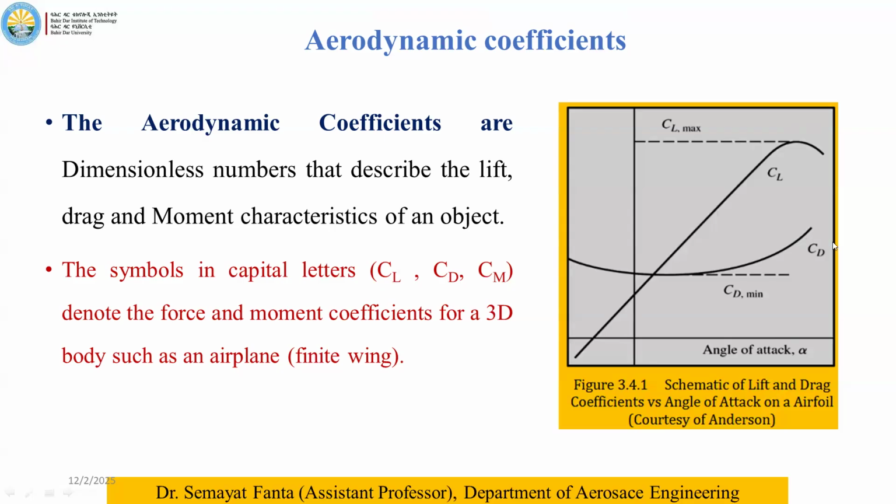Minimum drag is obtained at the intersection point of CD0 and CDi, where CDi is induced drag and CD0 is parasite drag. In the curve of drag versus velocity, they intersect at some point. That is called the minimum drag point.